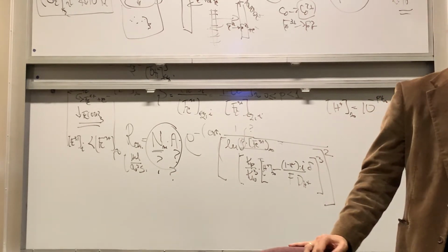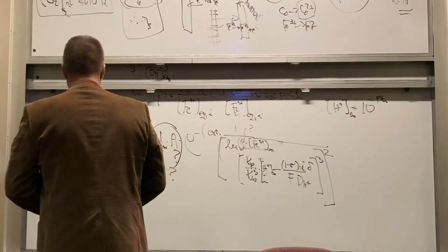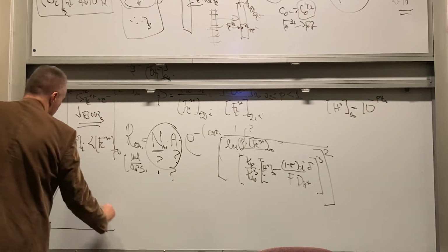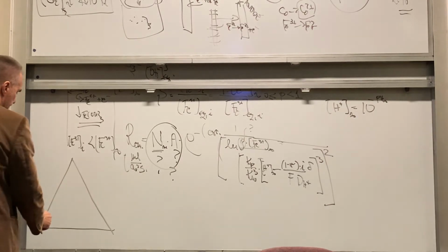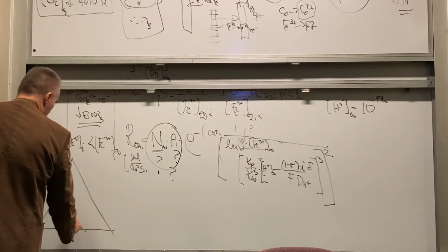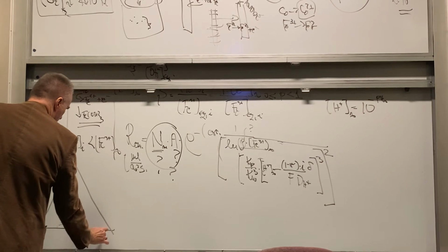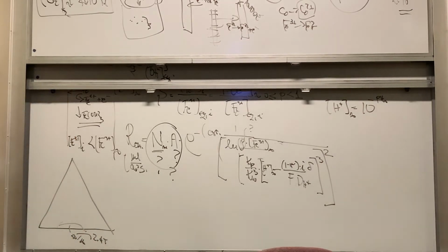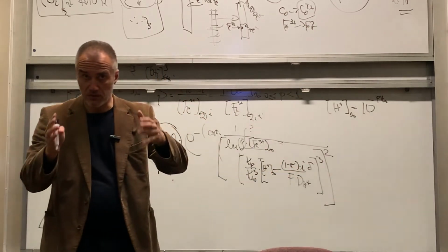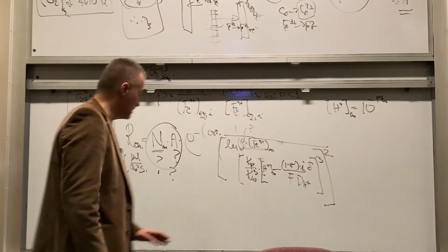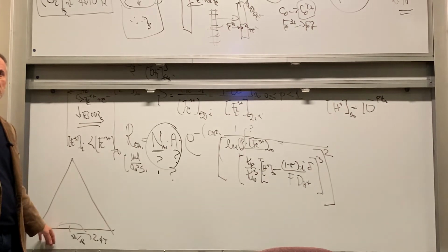Number two is that if you would have a perfect material, for example, and I'm going to use here, I think I sent you material where you have a ternary diagram, but there's a phase here, which is about cobalt iron 50-50, and it has a 2.4 Tesla magnetic moment. So if, let's say, I tune my process, with my concentration of iron and cobalt in the bath at the current density, that should give me roughly 50-50, plus minus 2% doesn't matter here, moment should be 2.4 Tesla.